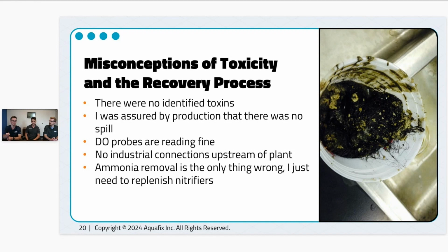They can build up around DO probes, so you can get a bad reading that way. So it's always best to maybe have multiple probes on site. And once again, microscopy can help you because low DO filaments are very quick at showing up under the microscope if there was at all any sort of low DO hit or anything like that. So keep an eye out for those. From there, it's really straightforward. It's just simply increasing your oxygen content.